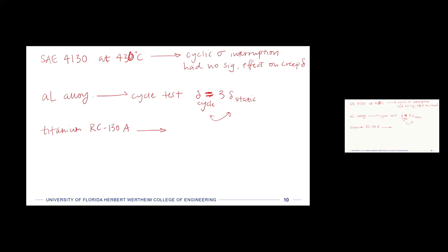They didn't do a true creep strain experiment on this one, but rather were looking at the stress rupture time. It does not say what the temperature was for this experiment, but it was a high stress level for 80 hours. I'm assuming it was high. So stress rupture time increased by a factor of 5 when the stress was cycled.